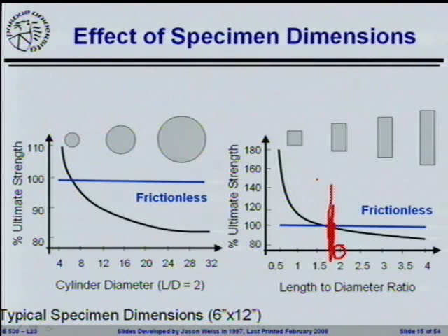So you go out to your 4-inch industrial slab and you take a 4-inch diameter core. And you trim off the ends and you bring it back to the lab. Now you're testing a cylinder that's 4 inches tall with a 4-inch diameter, which means it has a length to diameter ratio of 1. You would expect to get a higher strength unless you do something to account for the ends. All right, so you need to be very careful when you start using these types of altered specimen geometries for failed materials, that you properly account for things that could overestimate the strength in the system.